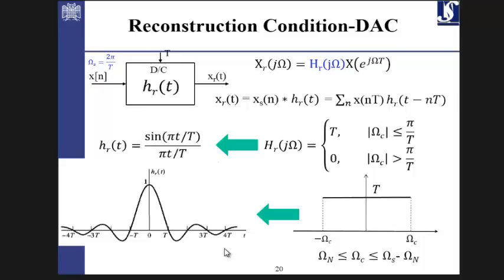In some cases, for example, 16 kilohertz, 2 times the Nyquist frequency makes sense, but not more than that. After some point the resolution is saturated. You can get 1 megahertz of sampling, but the result would be quite the same as 16 kilohertz. So why are you doing that? You're not economically using the memory.